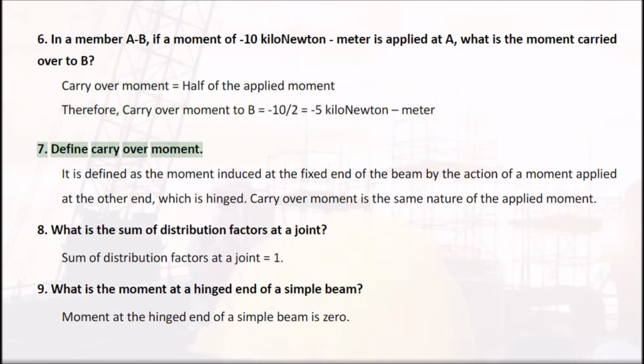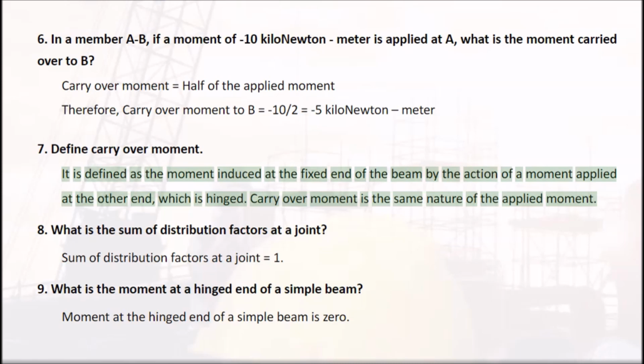7. Define carryover moment. It is defined as the moment induced at the fixed end of the beam by the action of a moment applied at the other end, which is hinged. Carryover moment is of the same nature as the applied moment.